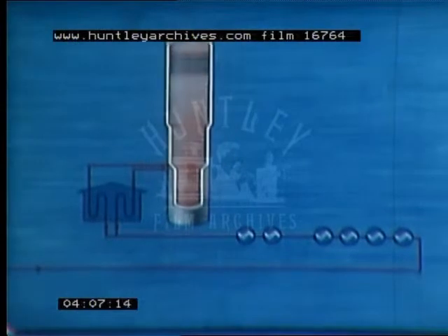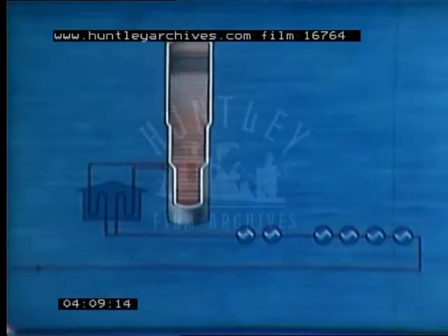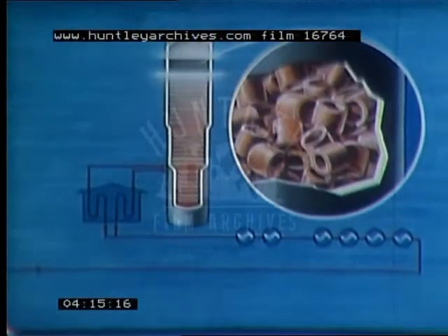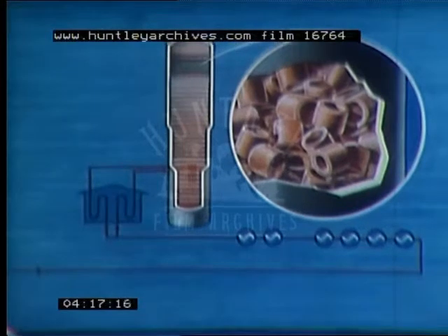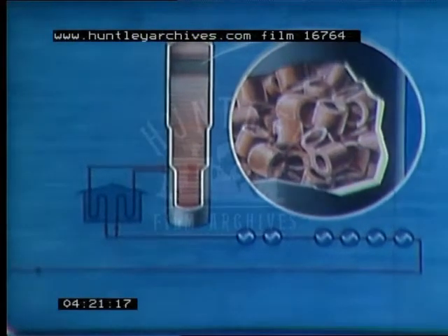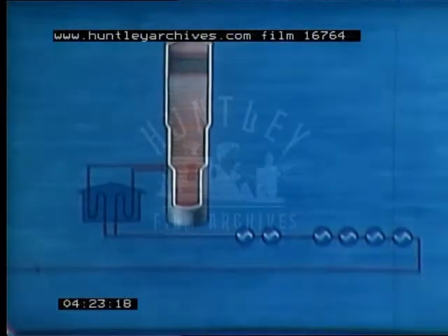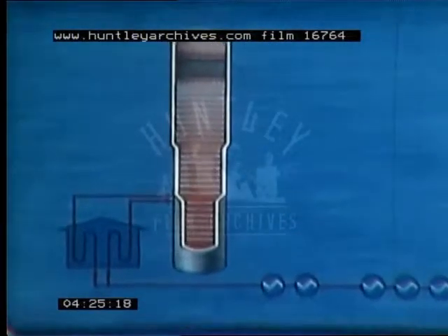This particular tower has 25 trays, the top tray being about 3/4 of the way up the tower. Above the top tray is one section deeply packed with earthenware rings. The rings are about 4 inches in diameter and loosely packed. This part of the tower is called the packed section. It serves the same purpose as several ordinary trays, and at the same time acts as a spray trap.